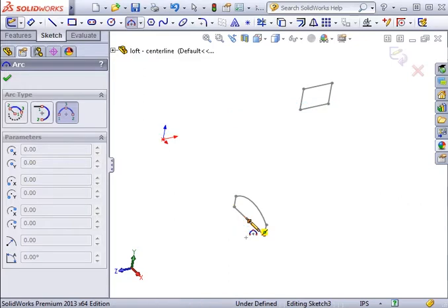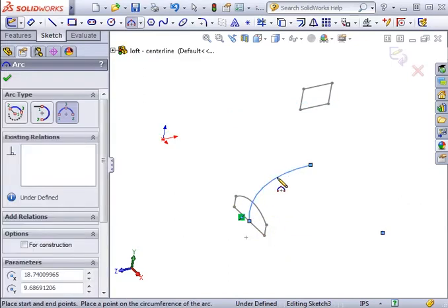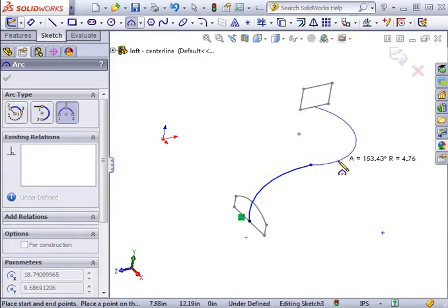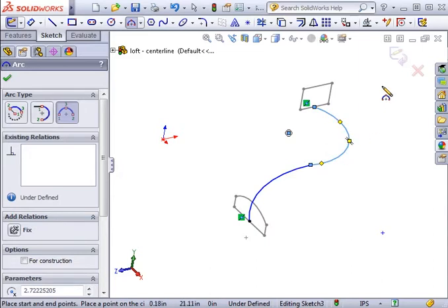One thing to keep in mind about this sketch is that it must intersect each profile. This doesn't mean it has to connect from point to point. It just has to be attached somewhere along the profiles.